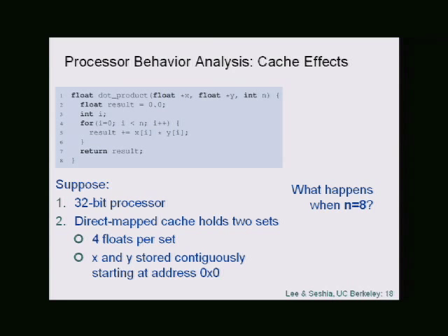Okay, so how do things work currently in practice? If you take the state-of-the-art tools, this is what they do. State-of-the-art industry tools. They have engineers who pore through pages and pages of documentation on processors, and they manually construct a processor behavior model. Basically, they model the cache and they model the pipeline and they model everything very carefully, and then at every basic block, an engineer thinks about, well, what happens if I execute this basic block? What happens to the cache? What happens to the pipeline state? What happens to the branch prediction unit? All of that. So you have to think about all of these things.